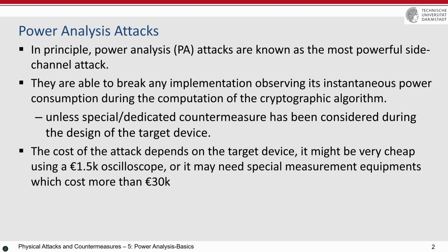But usually for us, depending on the implementation, if the implementation has a very high amount of power consumption and the power consumption is highly dependent on the data that it processes, meaning the leakage is very high, then normal and cheap oscilloscopes are enough. But in some other cases, if the devices are new, for example, a new mobile phone with a new technology of, let's say, 6 nanometer, the amount of power consumption is very, very small and the clock is very fast, then you need a sophisticated setup and devices. Then probably this 2,000 euro oscilloscope is not enough.